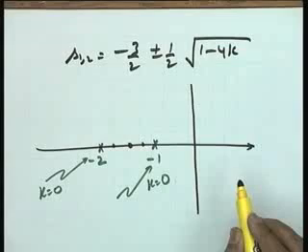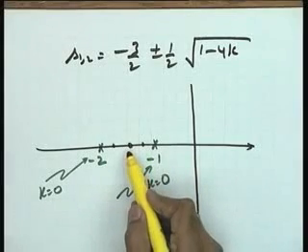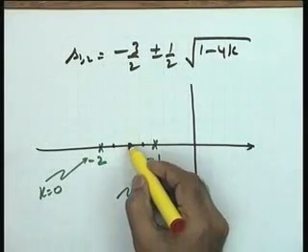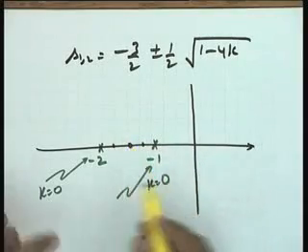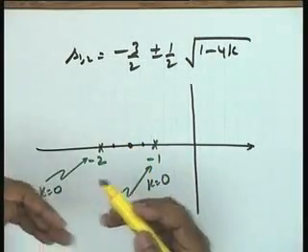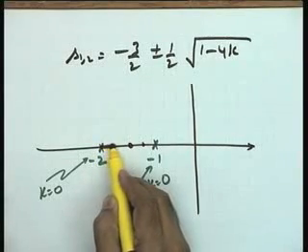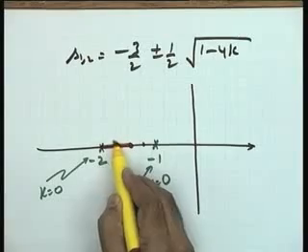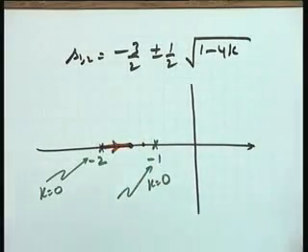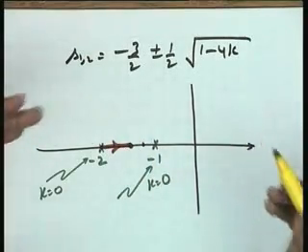At K equal to 1 by 4, the two poles are repeated and real, and they are located at this particular point. So, please note what is happening in terms of a locus. If K is increasing, one of the roots is moving this way, I can make an arrow here. You can check this by simple calculation, this being a simple quadratic.